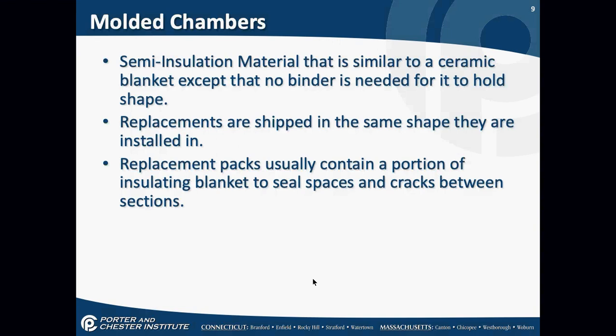Molded chambers are by far the most frequent combustion chamber you're going to find right now. It's a semi-insulation material. It is delicate, similar to the ceramic blankets, but nothing is needed to hold it in shape. Replacements are shipped in the same shape that they were originally installed with. Replacement packs also contain a portion of insulating blanket to seal spaces and cracks between the sections.